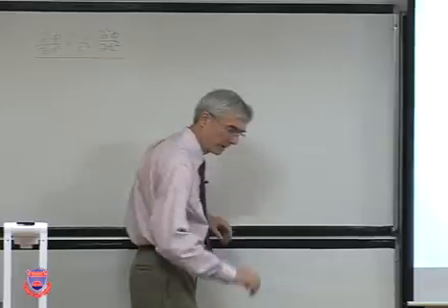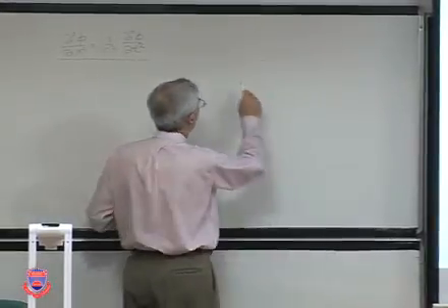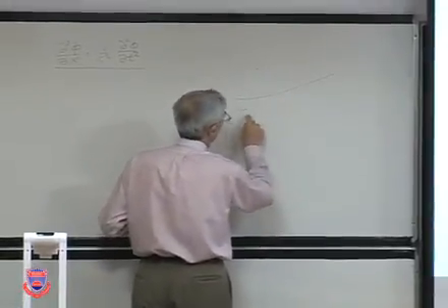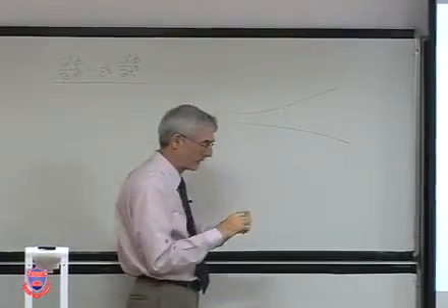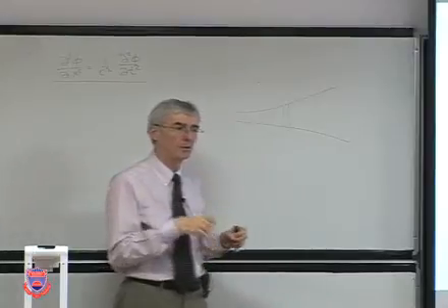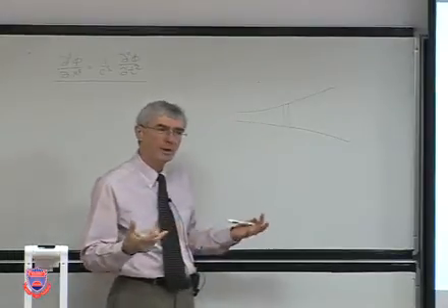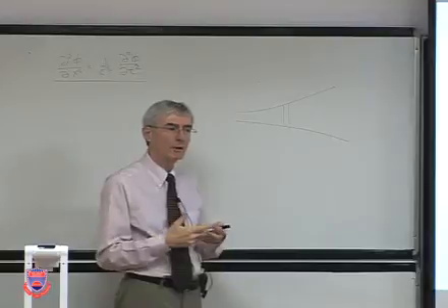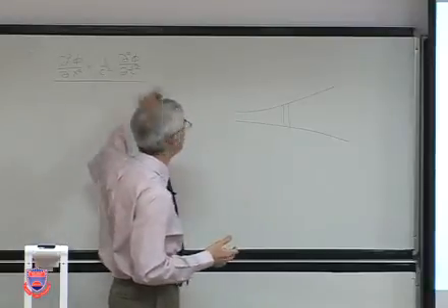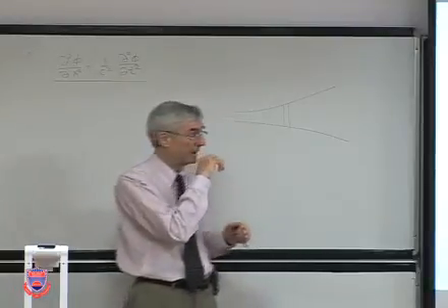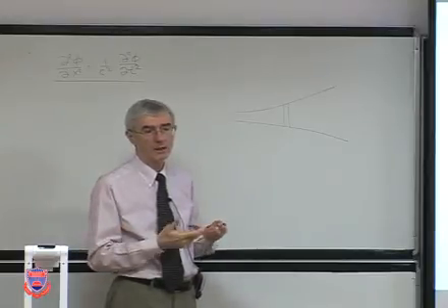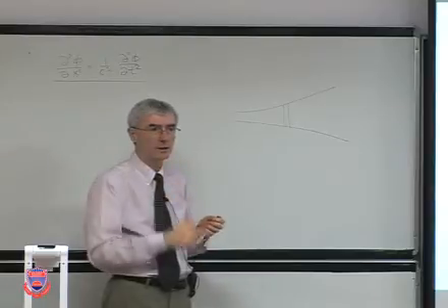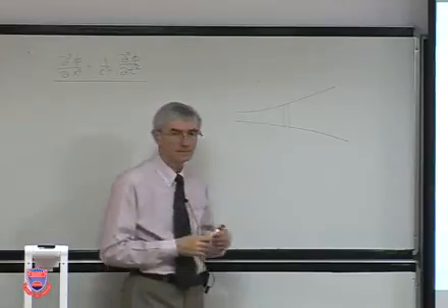Just very briefly, what we did was take the exponential, a varying section. We rewrote the continuity equation and used the linearized momentum. Once again, we rederived the wave equation, but using the velocity potential, and then we solved it for a particular change in the horn cross-section.